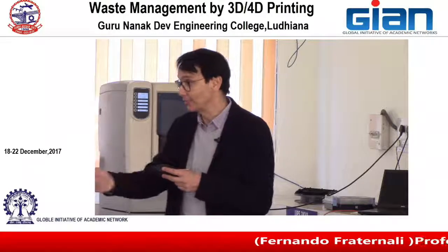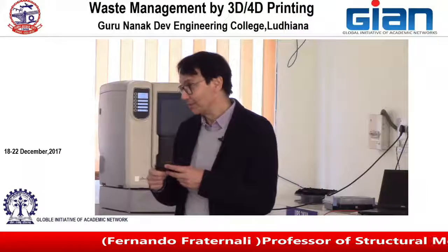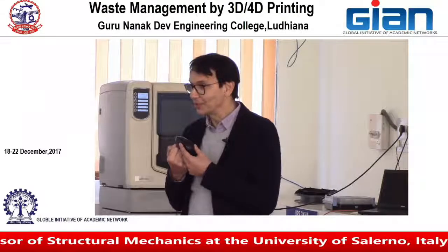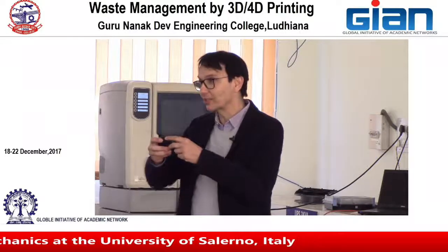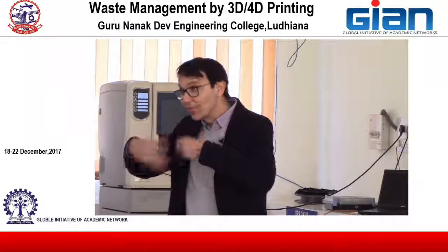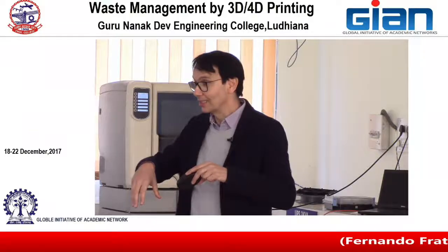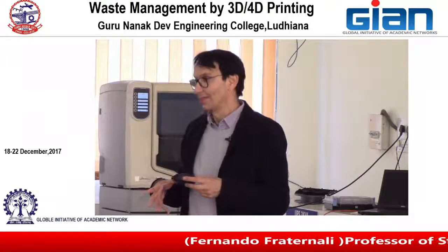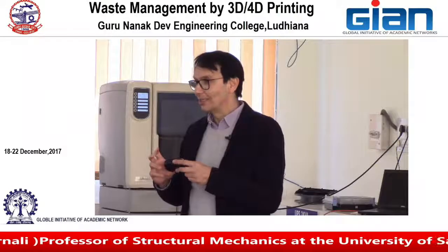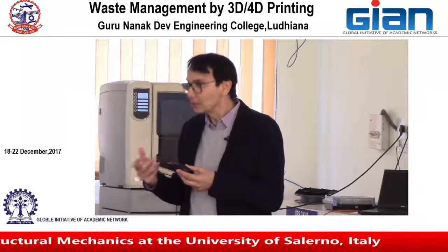We are spending some fracture energy, but we are gaining some elastic energy, because if we crack this, suddenly the body releases some elastic energy. So when those two terms balance, fracture occurs.